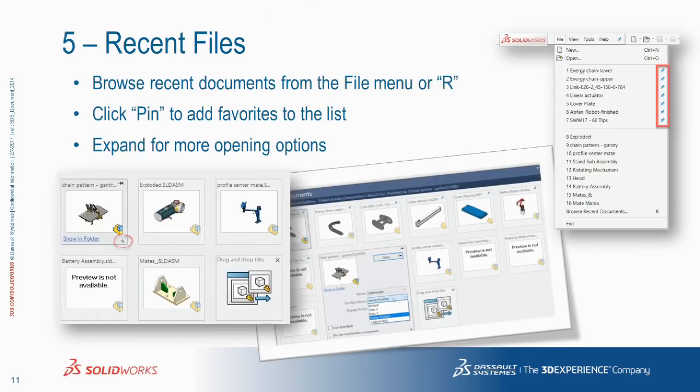Tip number 2. All right, recent files. I hope you guys are using this. If you have files that you like to have access to all the time, you can use the recent files to pin your documents, right? So you hit the R key, it opens up this nice big window with tiles of all of your recent components, or the components that you have pinned, your favorites, we'll call them, okay?